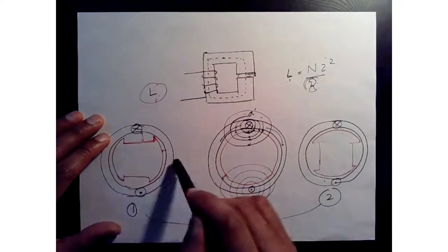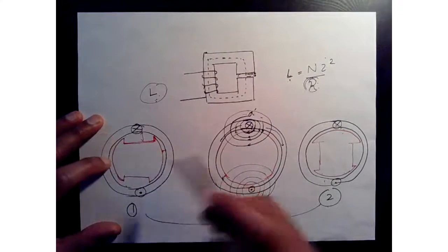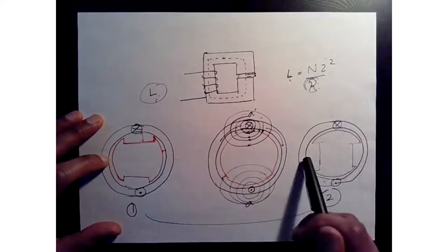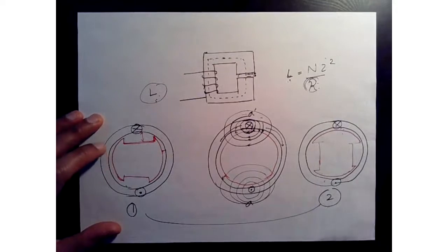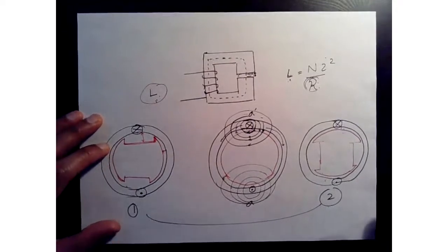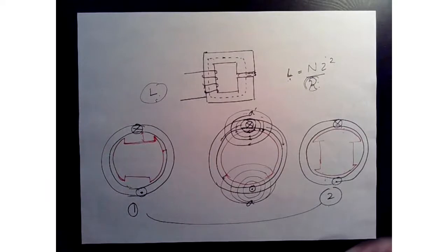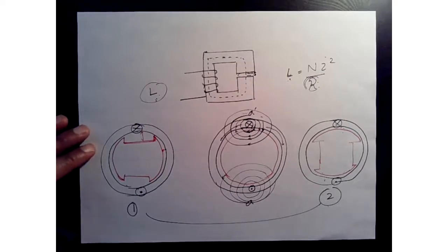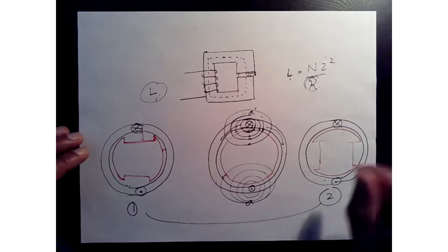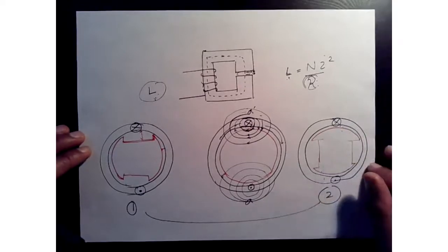In this case, it will see a very small air gap. In this orientation, it sees a much larger air gap, which will influence the inductance. And when we look further into synchronous machines, we will talk about L_d, D-axis inductance, and Q-axis inductance. When they are different or when they are equal, we can discuss depending on different machine structures. All right, I hope that was helpful.